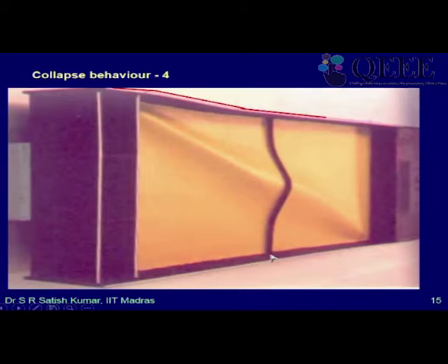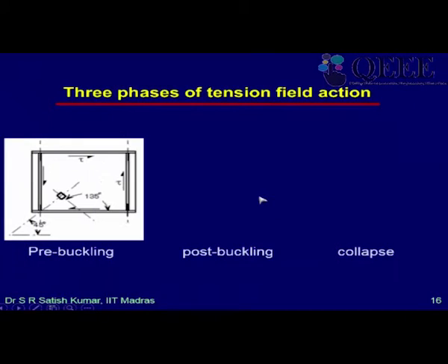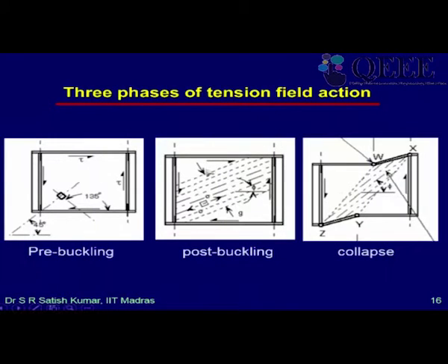So this entire panel has now buckled, as this is just a line or a very nominal stiffener which couldn't prevent buckling of individual panels like this, but two consecutive panels have together buckled, and the tension field cuts across them. Okay, so this distance is S, and that can be calculated, and we can tell at what load this collapse will occur.